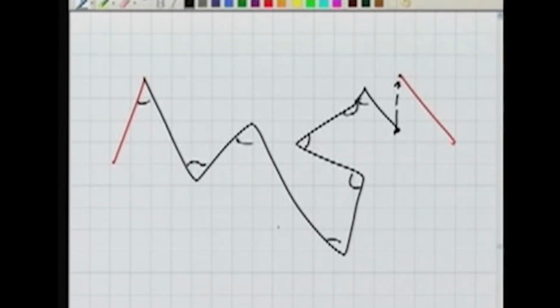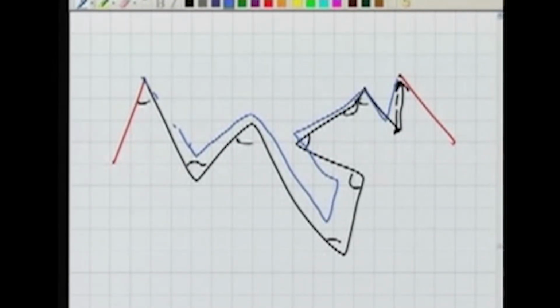So what we want to do is apply a correction to it. I want to take it here to the known position. So each and every line will be shifted accordingly so that it reaches here. So we are applying a correction to our observed values so that we are adjusting for the errors. So we can make use of these known lines in the link traverse for adjusting our open traverse.